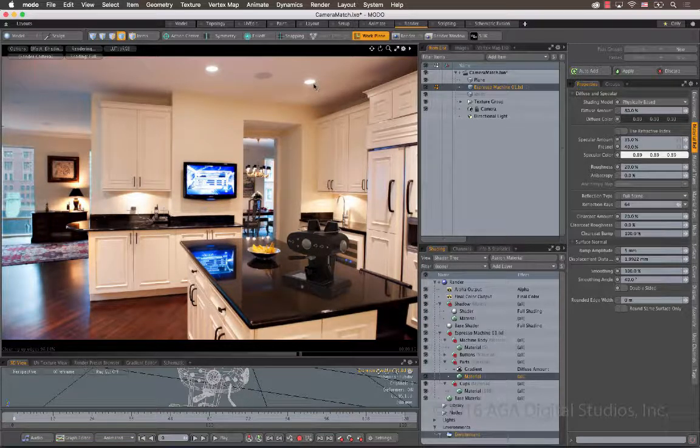You can match these lights as well. This also is what this is great for. Not just putting objects in, but putting lights in. I want to match a light in these spots in the ceiling. I can do it very easily simply by just adding a spotlight and lining it up because, well, I've done my camera matching, so that alignment is no different than lining up an object on the counter. So try that out. Some really cool stuff.